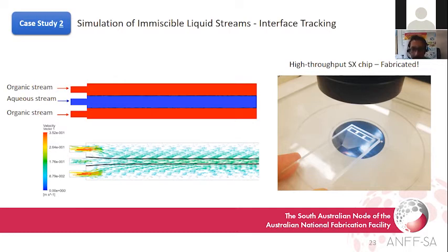To summarize this case study, the simulation helped here to accelerate the commissioning of the device by providing a reference to find the best operational condition of the solvent extraction chip. It was well used to visualize the fluids interface and find the surface area between two phases, calculate the mass transfer, and estimate the efficiency of the device.